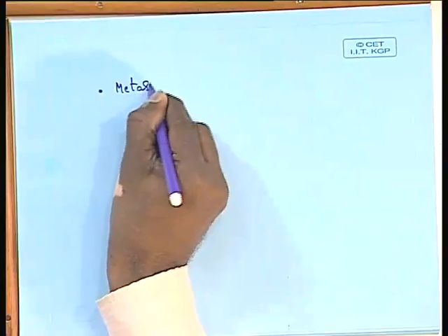What is the advantage of extension of solid solubility? Yes. You can get solid solution hardening, you can get precipitation hardening, extra precipitates you can get. Volume fraction of the precipitates can be more. So that is one way. Then what are the other advantages? The other advantage is you can get metastable microstructures.